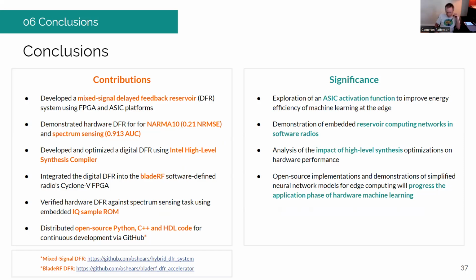The HLS tools typically just make use of a floating point core, a very general purpose core that is parameterizable in terms of the size of a floating point word, and is able to implement a variety of functions, arithmetic and other things. So in a sense, that's not really too different from what a processor is doing.